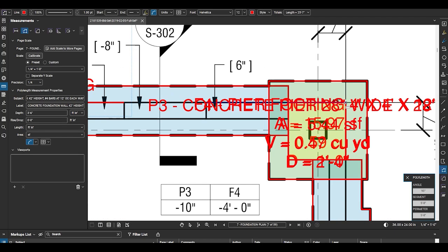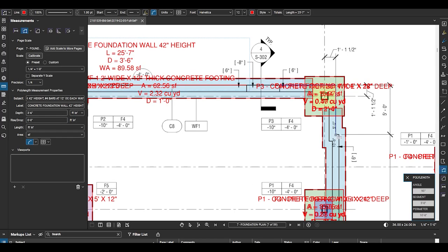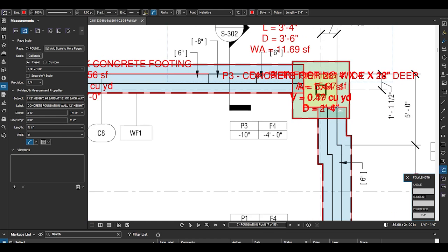This gets a little tricky, but if you take your time to identify the various instances and changes in wall height, you can accurately account for every wall. The C10 foundation wall only occurs at that vestibule bump out location and terminates at -8 inches, and then it's got a C8 foundation wall on top of it.